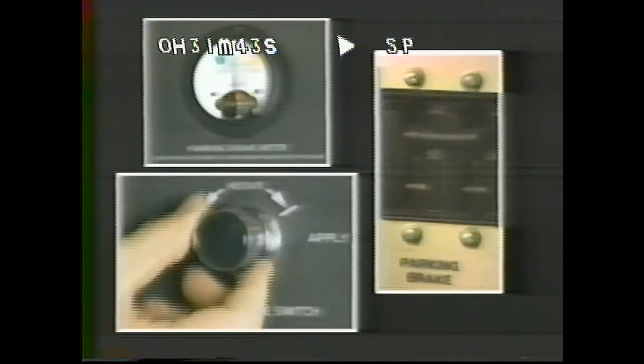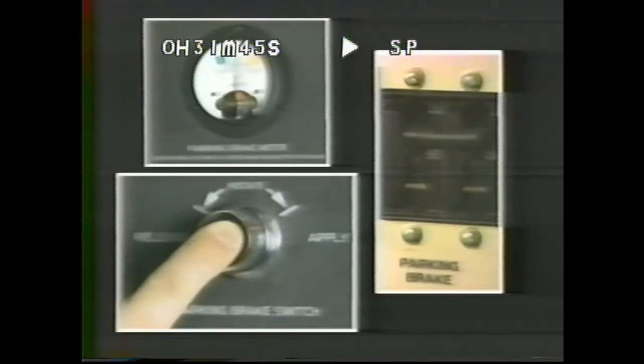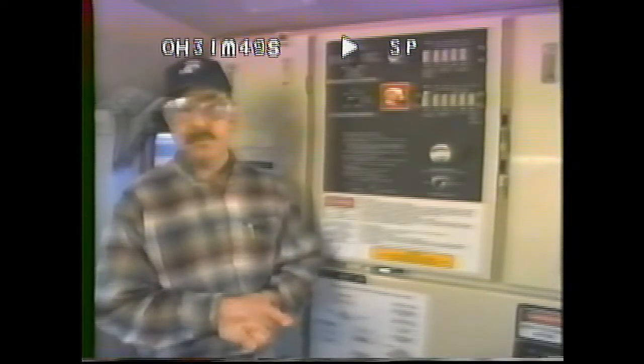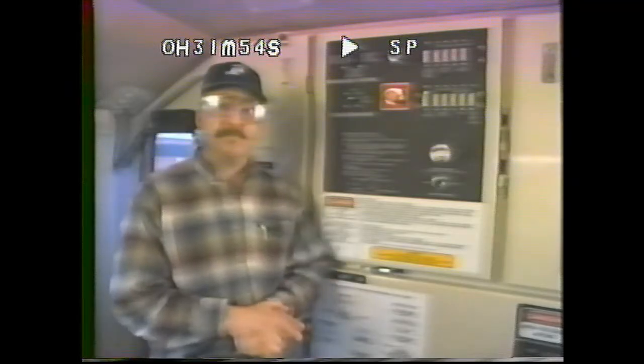Now that we've covered some of the new components and features of this locomotive, let's talk about operation of the SD-80 Mac. We've already covered the operation of the electric parking brake. But what if the locomotive is shut down? Well, as long as the batteries are okay, just make sure the parking brake circuit breaker is on, and then just operate the parking brake switch. But what if the batteries are dead? Well, use the crank. Let's go down and take a look.